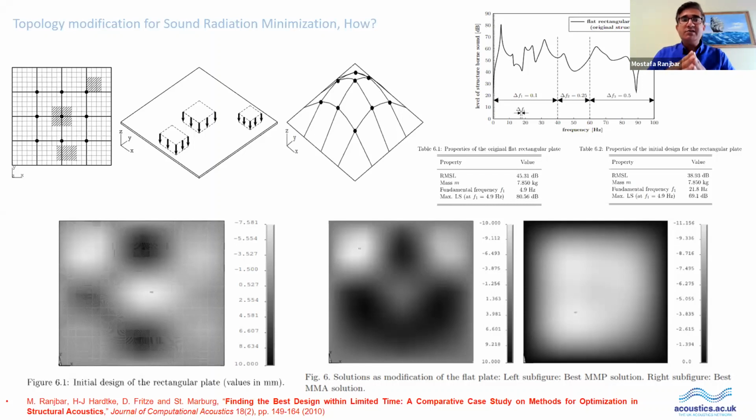optimization. Here we are changing the outer surface of the structure. For a muffler, we are changing the internal geometry of the muffler. And for metamaterial, we are also changing the internal structure. So this concept can be useful for reduction of the radiated noise from the structure.